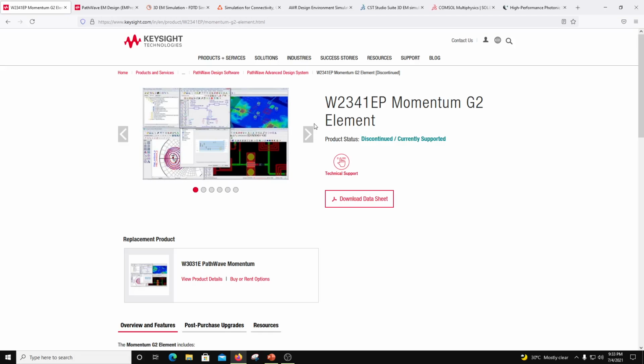So in that case you take a geometry which is usually planar. What I mean by planar is that it is made up of sheets of metal which are separated by dielectrics or which may be connected by vias. So that is called planar. It's in one plane, the xy plane, and the z direction is basically an algorithm, a computation of z currents. In method of moment there is nothing to consider z currents, so thick metals cannot be considered in method of moment per se, but when you say 2.5D simulator, you can use some algorithm to work on the z direction currents.